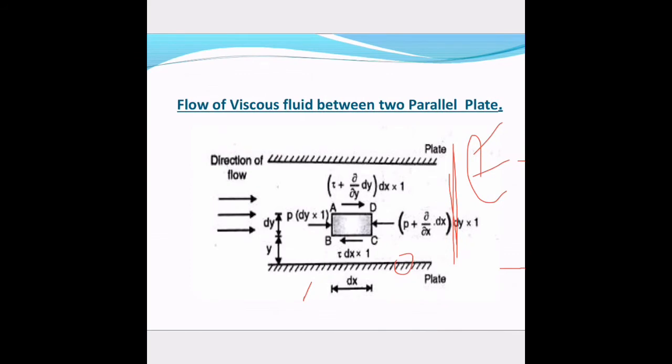Again, if we talk about shear stress, I think all of you know what shear stress is, isn't it? Force per unit area. So shear force will be shear stress into area. Using that equation we have to find the shear forces acting on the walls AD and BC of the fluid element.